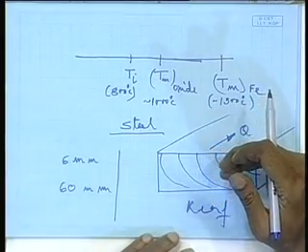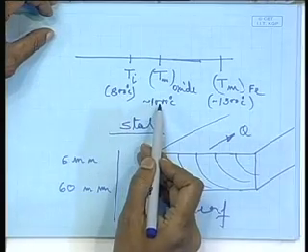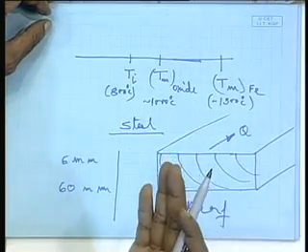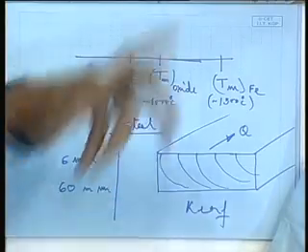Well, so one of the solutions is to cut from both sides. No, that we cannot do; instead you increase the heat content of the gas mixture. Now, I can cut it faster provided I can attain these temperatures, 800 to 1000 degrees centigrade, faster. If I can attain them faster, I can move the torch faster and cut faster. That means I have to use a heat source which will have more heat content, because how much heat the oxyacetylene mixture will generate is fixed by chemical thermodynamics. You cannot increase that, so you can only increase it if you add some additional substance.